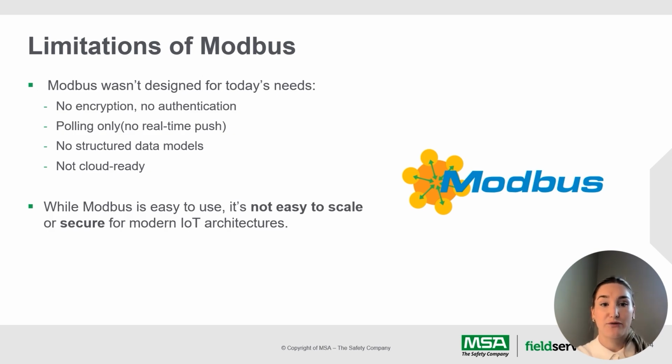It also was not built for the internet or IP networks originally. There's no native support for cloud protocols, no encryption, no session management, and no way to handle connectivity loss gracefully. So if you want to push Modbus to something like AWS, Azure, or any modern analytics platform, you're going to need an additional layer of infrastructure to translate that secure data.